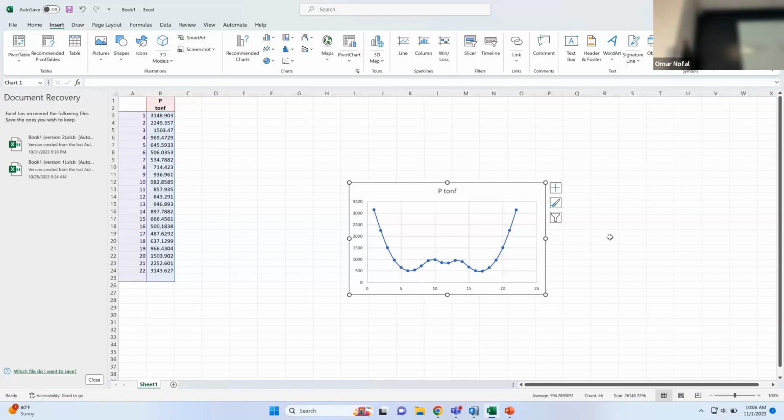And this core connected these two columns very stiff together. So they have a little bit of a stiffness that can take more tension or more compression. So more loads are transferred to these columns. So the internal forces went up a little bit. Okay. But however, when we go up with more stories, this effect can be decreased.